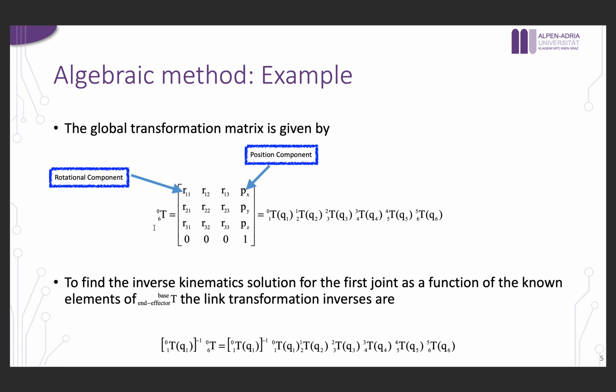basically what we need to do is first take the first term, which is the first transformation, t01. We multiply both sides of this model with the inverse of that transformation matrix. What is the goal here? The goal is that what I want to do first is to get theta 1 or q1 as a function of everything else. So I want to have a set of equations where in each equation I have one target variable, and we start with theta 1.